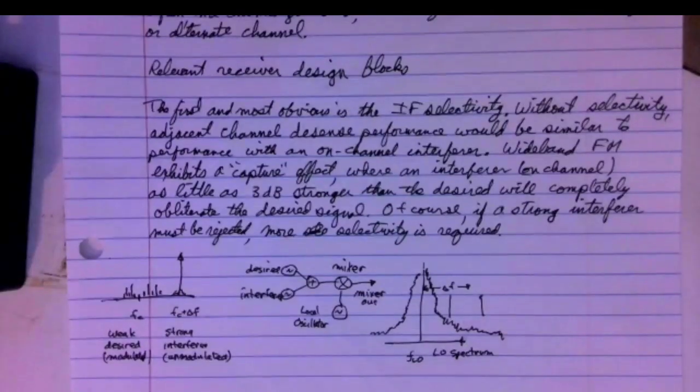With an FM communication, you might not even know that you missed something. Because it only takes a couple of dB and whichever is stronger wins, aircraft communications do not use FM because of the capture effect. Just a little aside.